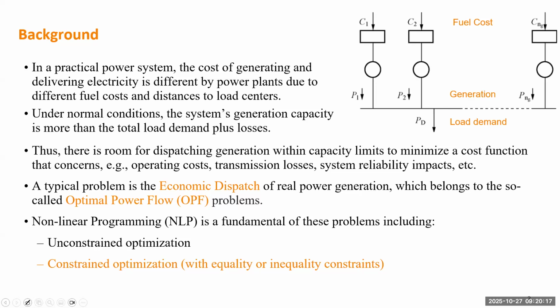For instance, when you plug in the generation at different power plants, then you calculate the minimal cost based on their fuel cost. But when you try those generations in your power flow problem, it doesn't solve the power flow. So even if there is a certain pattern you can dispatch generation in, it never makes the power flow feasible. So the engineer or the operator doesn't know how to implement such a solution. So they are not feasible solutions.